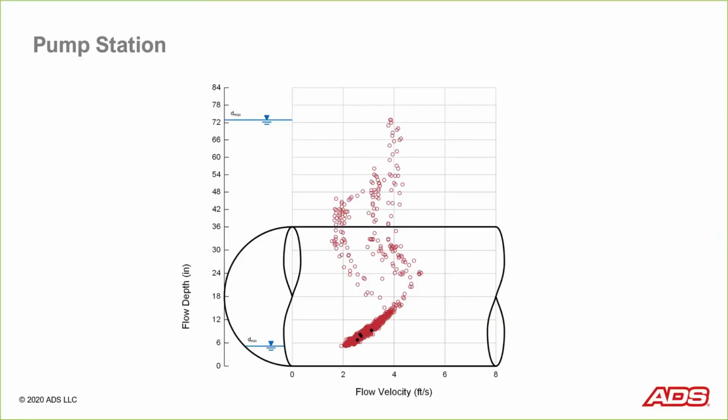Well, let's use some of the tools and techniques that we've talked about in some of the earlier stages of this webinar series. The first thing that I usually like to do is put a Manning equation on this graph. And you'll notice here I've done that with the Lanfear-Cole method. And you can see that curve goes right through this data in a very nice manner and gives us a full pipe condition right up here. But you'll notice we never quite achieve that. We start to see backwater and surcharge conditions before that happens. We can mark those conditions here off to the right.